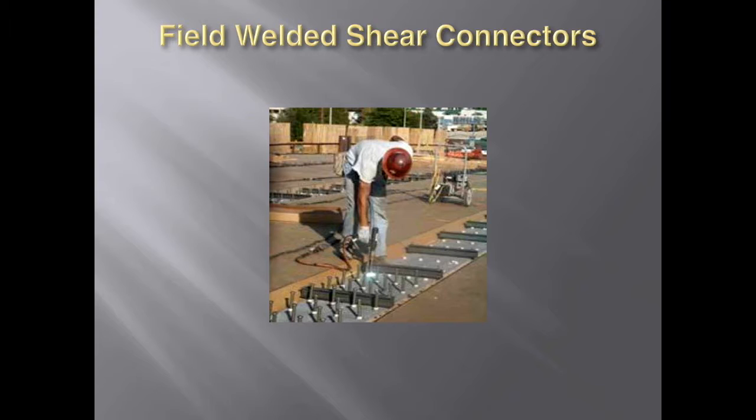So after the deck's up, you get a hold of us, we'll come out, and we can help do the studs, stud welding. Actually, there's a procedure that has to be performed before they start to make sure they're doing everything correctly. OSHA about 10 years ago decided that this was a trip fall hazard, so they said these have to be installed in the field rather than in the shop. Before, they were done in the shop, it was really easy for us to look at, and nobody had to worry about it. Now they're done in the field, and so somebody's got to be there to basically watch it.